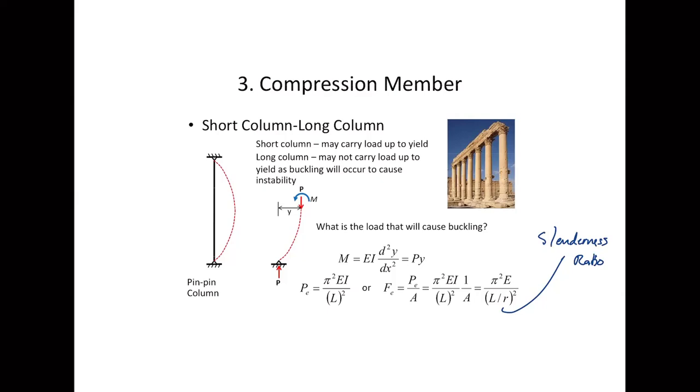And when we talk about, say, the clip, you see that she has a cross section that looks like this. So this axis is very strong, right? So you cannot bend your member about this axis, but this axis is going to be very, very weak. So it bends about this axis, just like your plastic ruler. So when you have a cross section that has two axes like this, you must check which axis is weaker, or I can say which axis is more slender, and that slenderness ratio is going to dictate the behavior of your member. Okay, from time to time you can have a cross section whereby you only have one, like a circular section. There's no weak or strong axis, right? There's just one L over r, that's fine. Or a square section, but in the general case where you have two axes, you must check both.